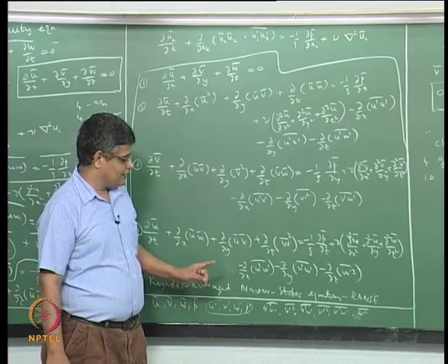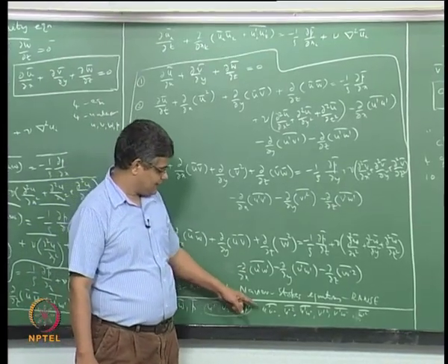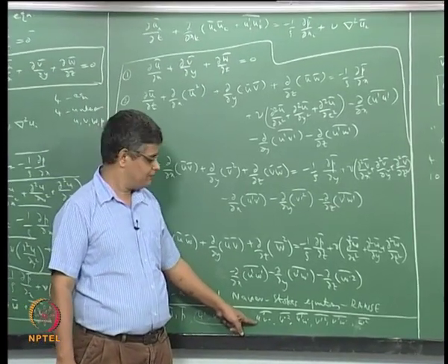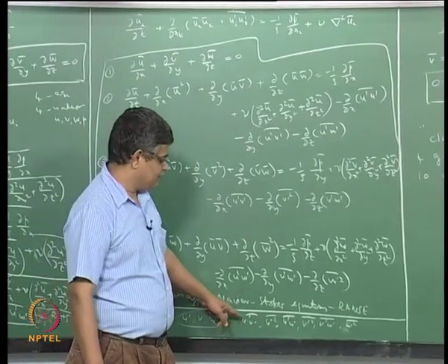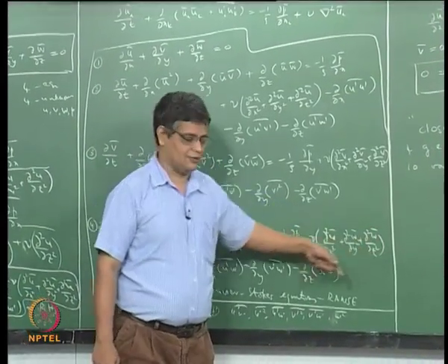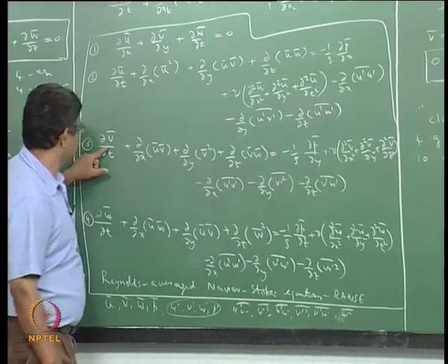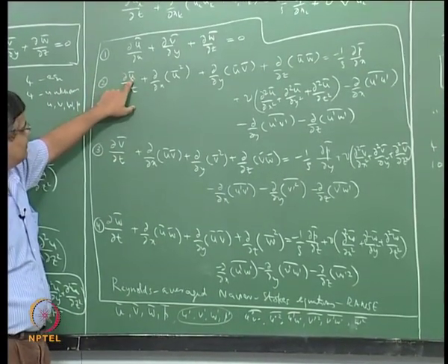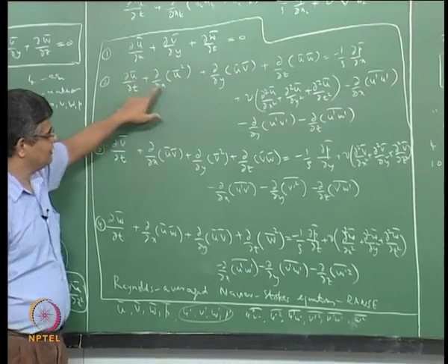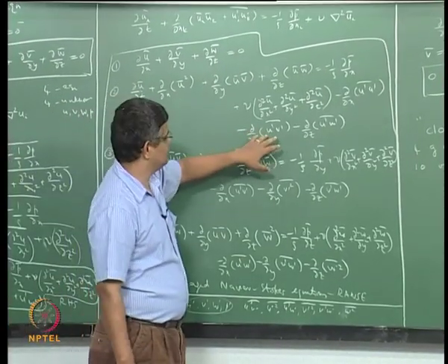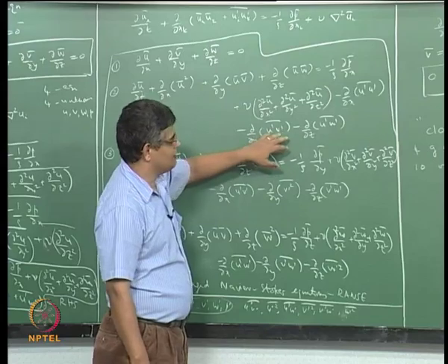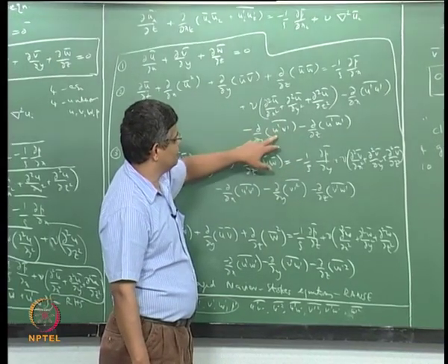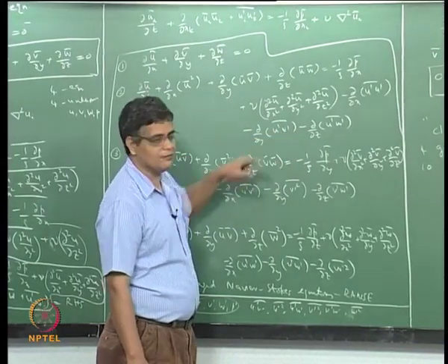But in the process of generating equations for these, we will find that we will be introducing more fluctuations. For example, in generating the equation for u bar, the time average of the u velocity, we had to introduce the time average of fluctuating quantities u prime v prime.